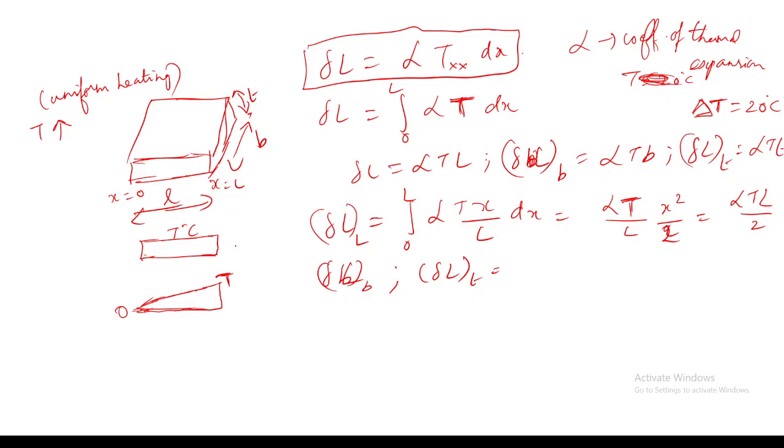So till now we have discussed the deformation due to temperature rise, but this is the case of free expansion. Free expansion means I have not constrained this bar in any degrees of freedom. All the sides of this slab are free to expand. So can I expect any stresses to be generated due to temperature rise? No, sir.